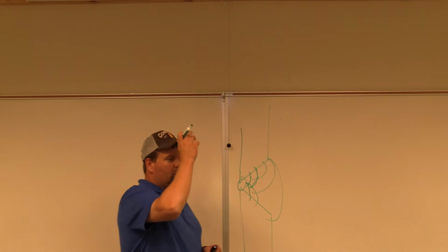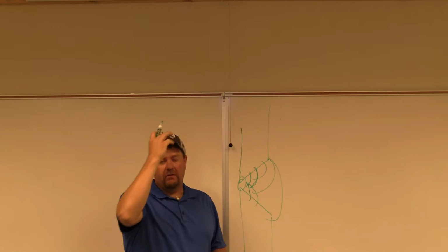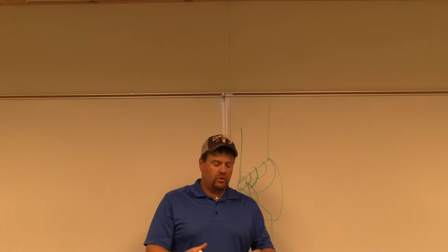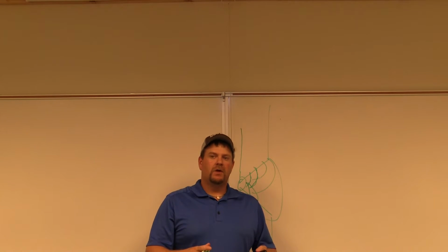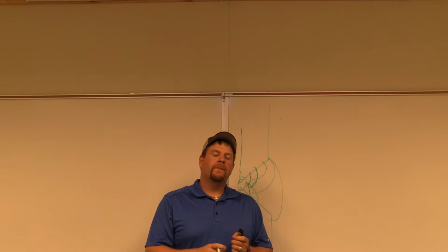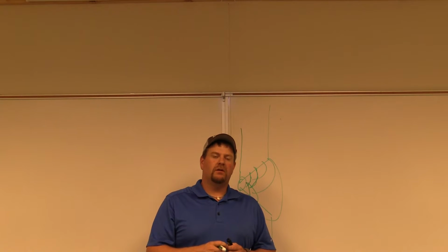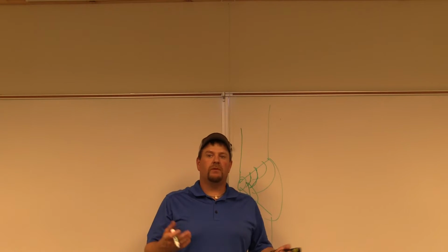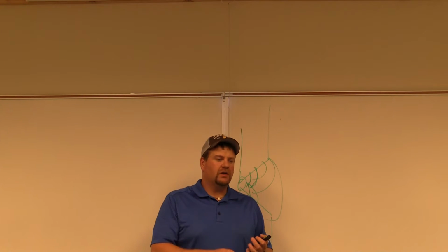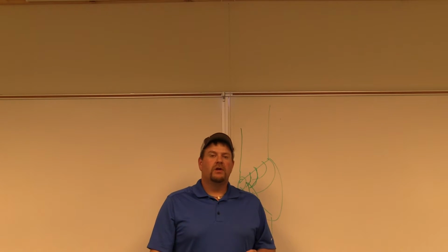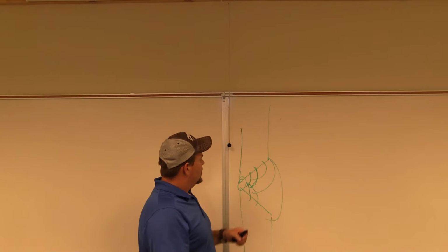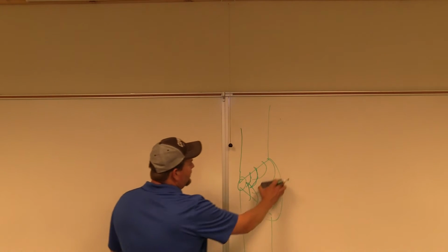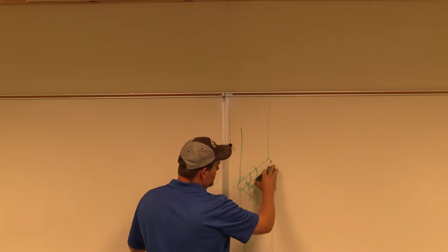Okay? Now if you notice, that's a mild steel filler metal, okay? But when you open up that wire, what does it look like? It looks like copper, right? So there's a coating on that wire that prevents it from rusting, which it has to. Otherwise, it's just going to be one big ball of rust. And then we've got oxides and rust within our weld. We don't want that. So what they do is they coat it in this coating to help prevent rusting and corrosion. So as we're welding this, guess what happens to that coating?